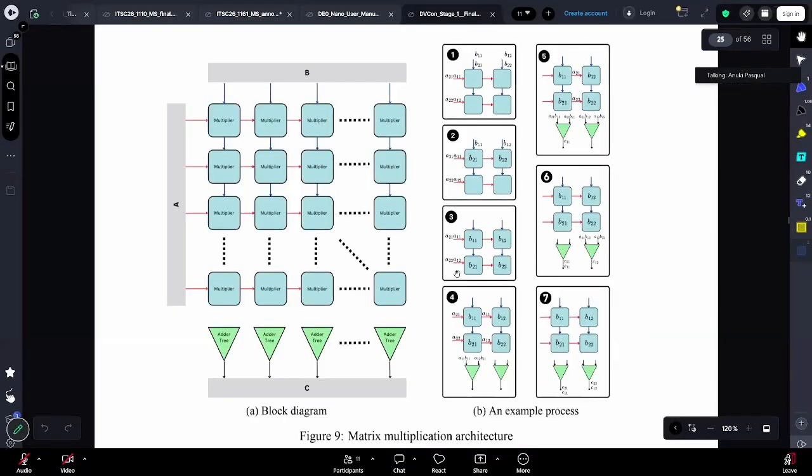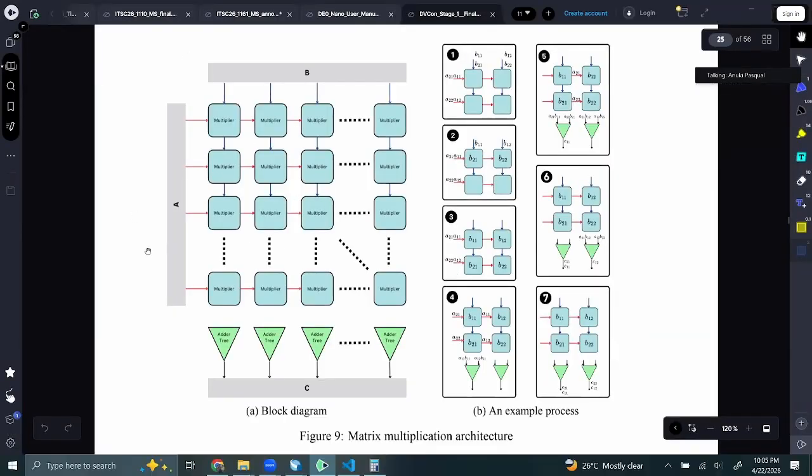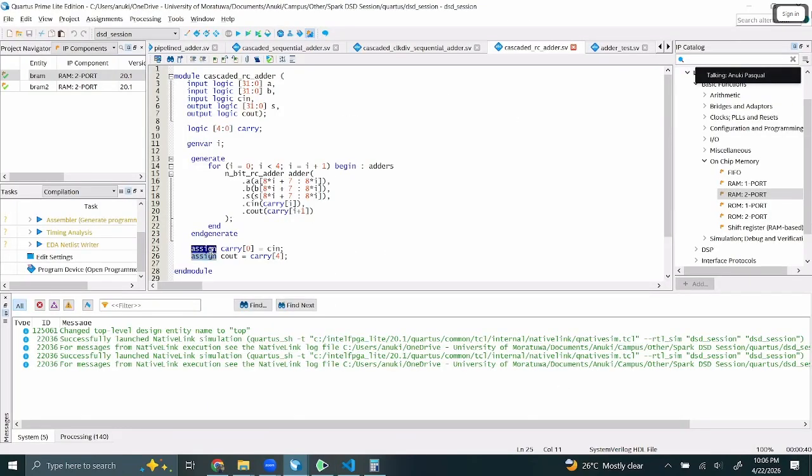Otherwise, if you are doing something like making matrix multipliers, hardware accelerators, then you will have large images that you are giving to the matrix multiplier. Then you can use VRAMs to store that. Otherwise, distributed RAM won't be large enough. So I think it will be helpful when you are doing more complex designs.